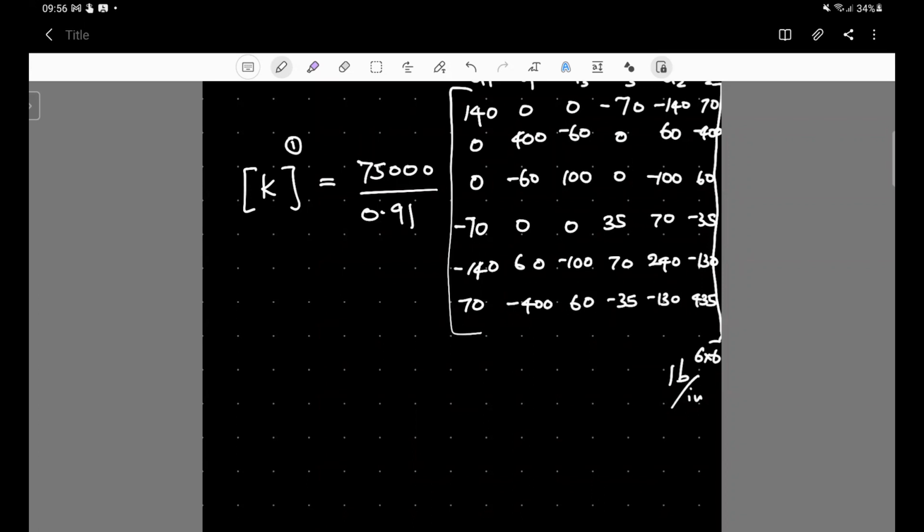the stresses vary linearly within the element, rather than being constant. In the constant strain triangular element, the strains are constant, of course, but in certain problems, if we are required to further complicate it, we need to add further degrees of freedom and use higher order functions to describe the displacements within the element.